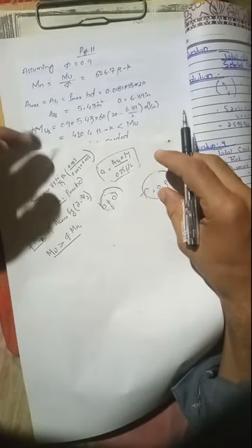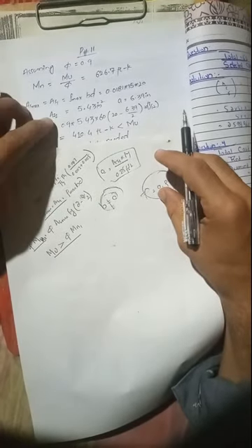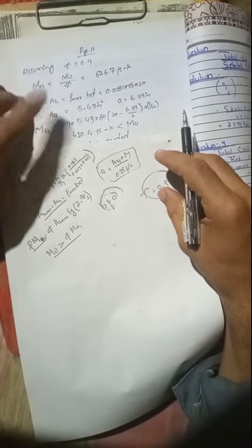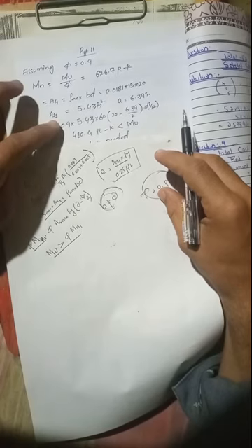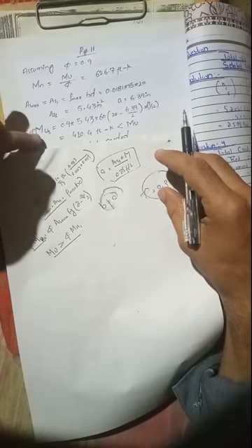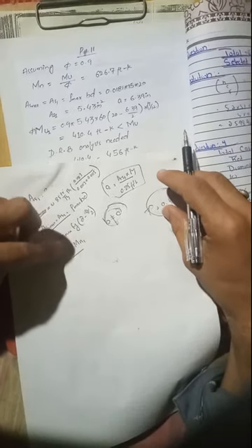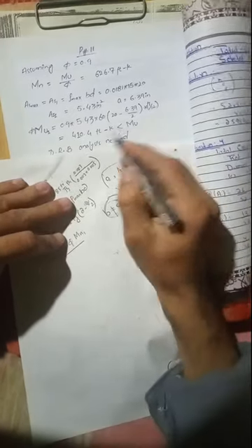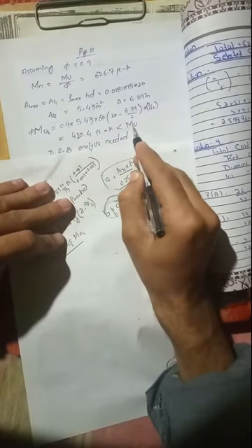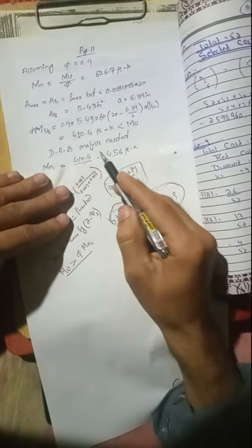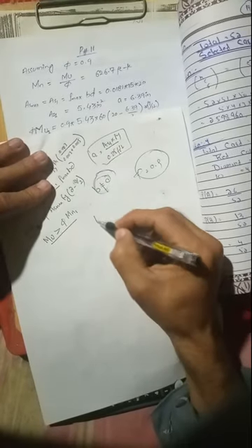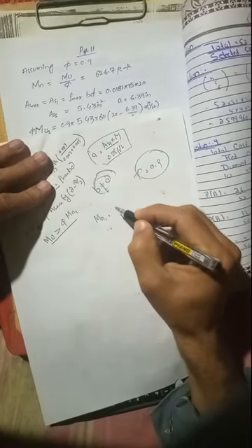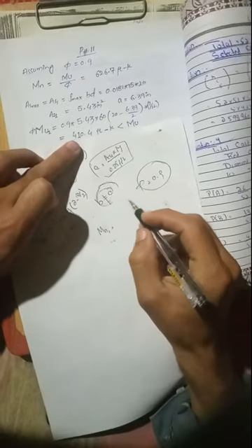As max, as I already explained, is also equal to As1. At this stage we can write that As max equals As1. Now find the moment capacity as I already explained in this formula, and we find 410, which is less than Mu. Mu is 564. So this means that we need double reinforced beam analysis. We need to find out the Mn1 value. So how to find the Mn1 value? That is the capacity 410.